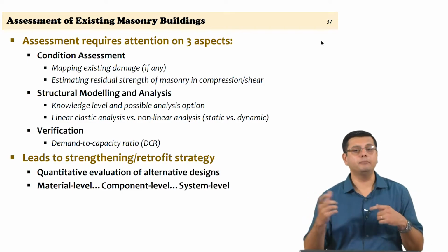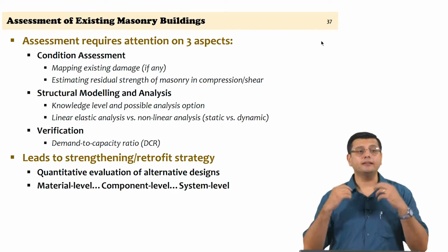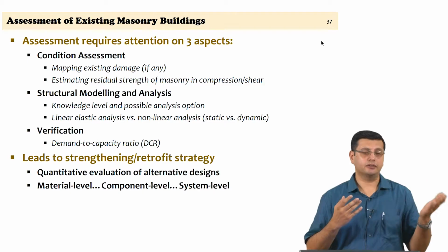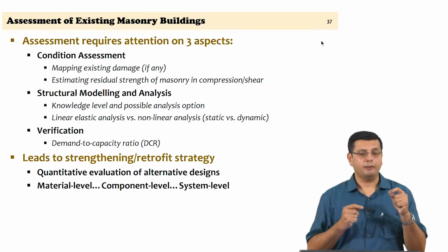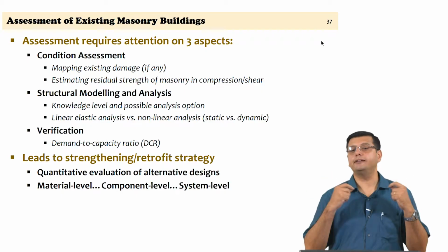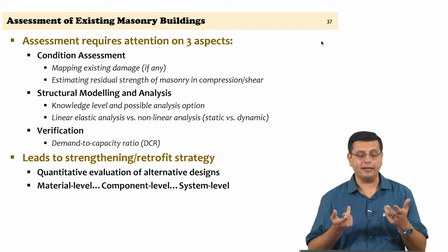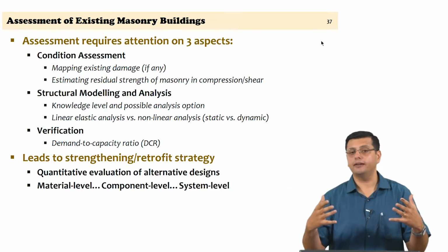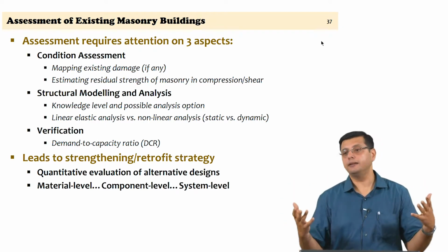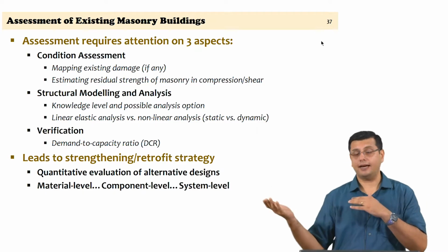In masonry, we have seen the importance of making the structural walls work together. The earthquake design and detailing requirements mandate that you must have lintel bands, you must have plinth bands, you must have roof bands, and these are basically at the system level trying to hold the entire structure together and ensure integral action against earthquakes. So, that is at the system level.